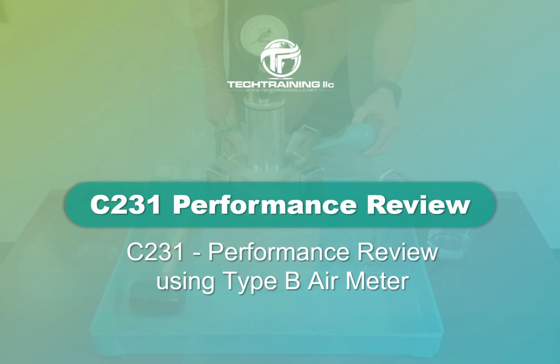Now that we understand the basics of ASTM C231, let's go through a detailed performance review. In this example, we will be using the Type B air meter. And since the slump of our concrete is greater than 3 inches, or 75 millimeters, we will be using the rodding method.